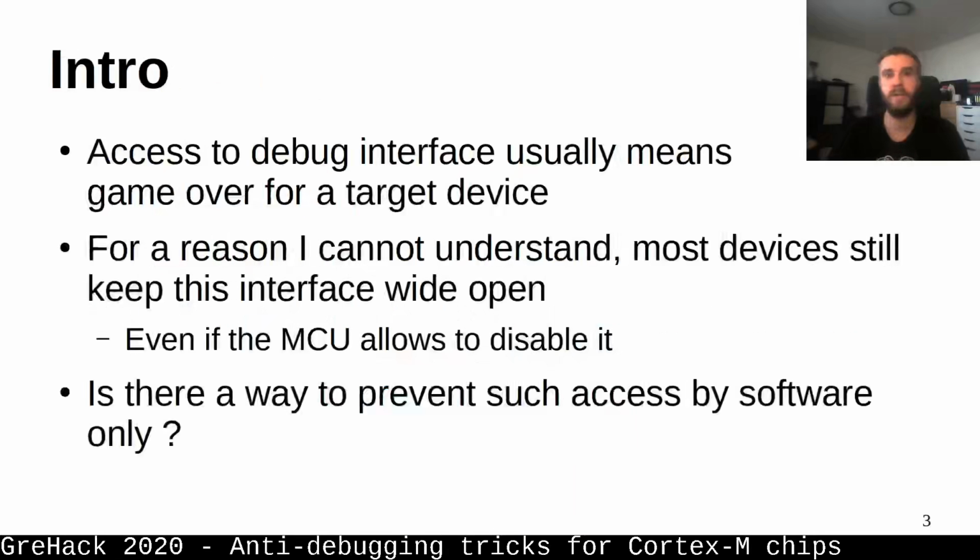On embedded devices, having access to the debug interface usually means game over. You have read and write access to the firmware, read and write access to the registers, and you can even look at the code while it's running to better understand what it does.